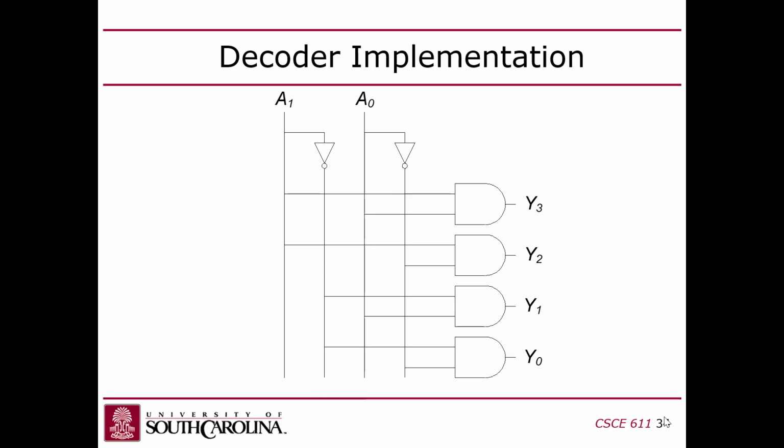And this is a possible decoder implementation where you sort of set up a PAL type structure. PAL or PLA, programmable logic array, where they show the 2 input variables and the complemented form of them, and you're connecting them to this array of AND gates.